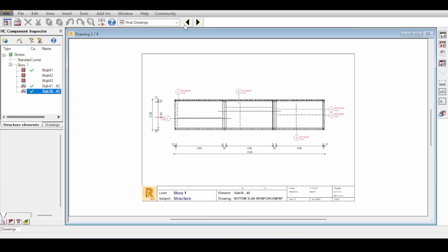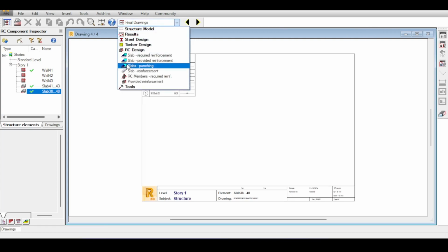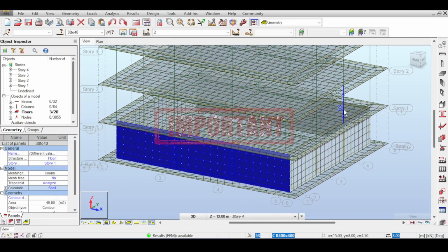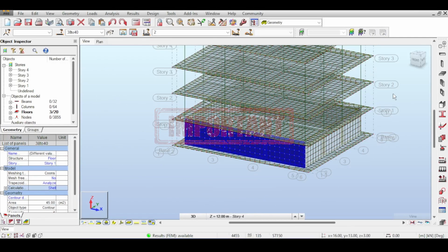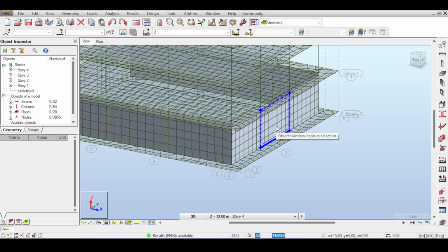So yeah, I think that I am genuinely happy now, and there is nothing I want to add here. So I want to go back now and just wrap it up again. To issue a stern warning, please do not, as tempting as it sounds to use walls, do not use walls when you have an area element with forces perpendicular to the surface of the element, because walls do not see those moments. Walls only see axial forces and moments that are around the vertical axis of the wall.